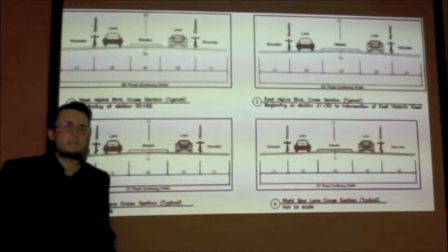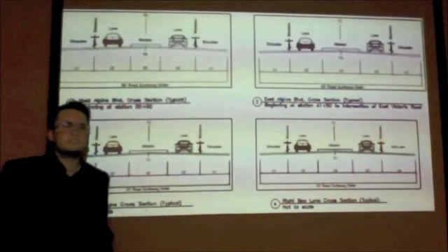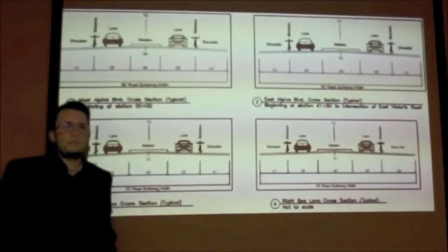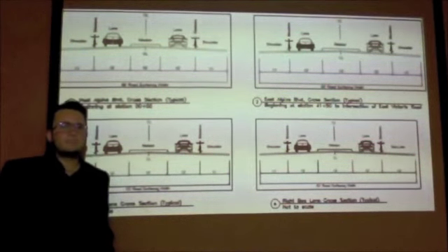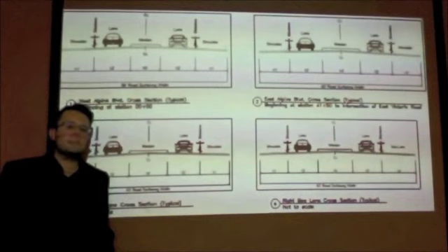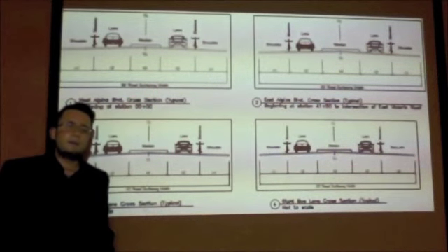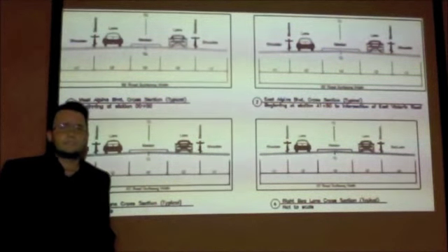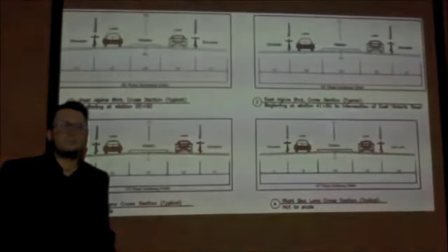Roads paved with this material generally experience longer service lives before maintenance is required. Rubberized asphalt generally resists the formation of cracks better than conventional asphalt. It exhibits more elasticity than unmodified asphalt, and it also shows a greater resistance to aging.